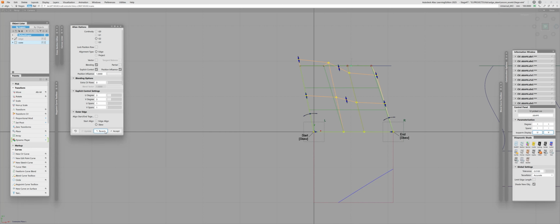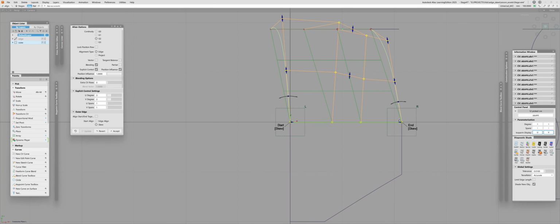But if I revert, trim, then align, and try to move, you're going to see that apart from the fact that the boundaries are not matching anymore, the skewing angle is not following the direction of the surface anymore. It's not changing. It's stuck in that arbitrary position. Once again, it's the resulting vector, but it keeps it and it's not changing anymore.